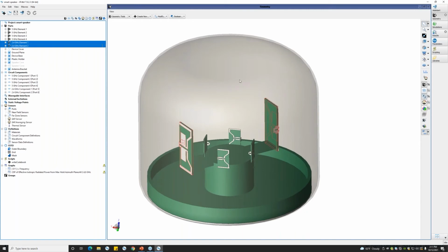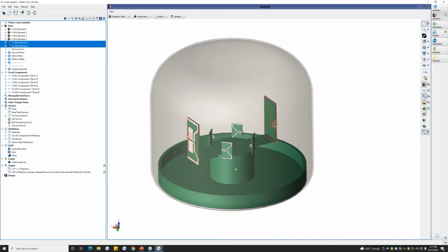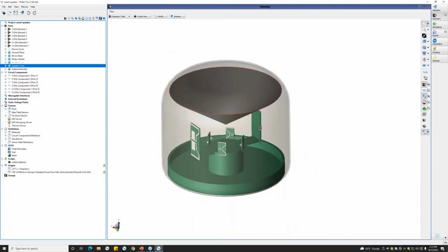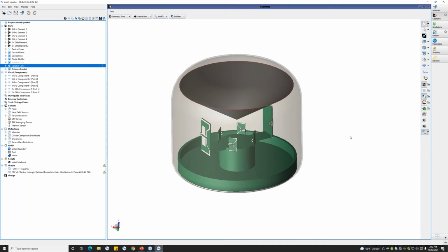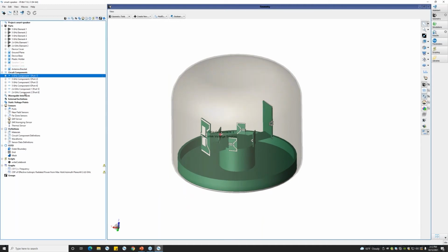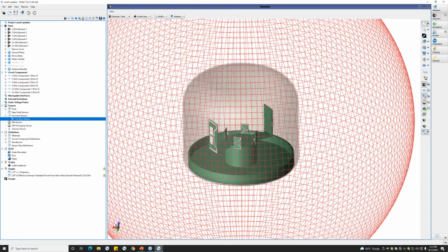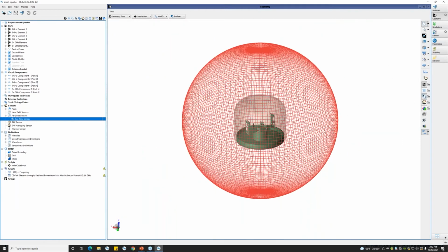And we have a translucent case that is covering the speaker, and we have a speaker cone which is also placed to include in the electromagnetic modeling of these structures. And each of these arrays are excited through lumped components, and I have set up a far zone sensor to extract the radiation pattern for these different arrays.